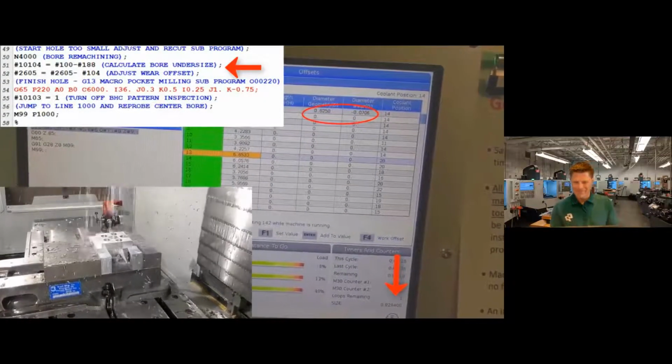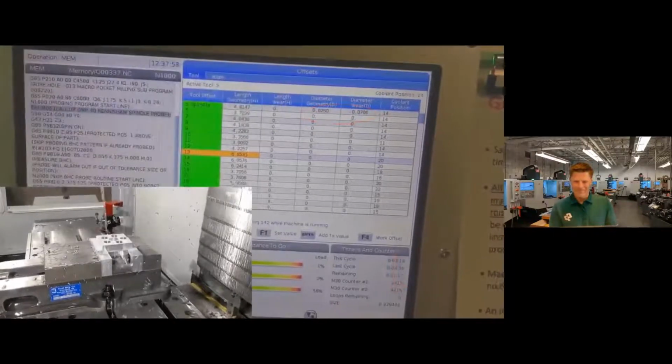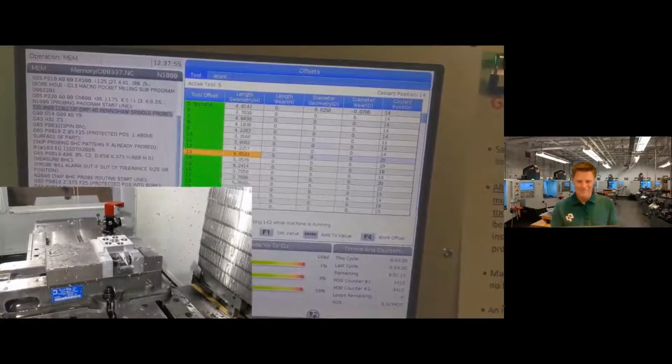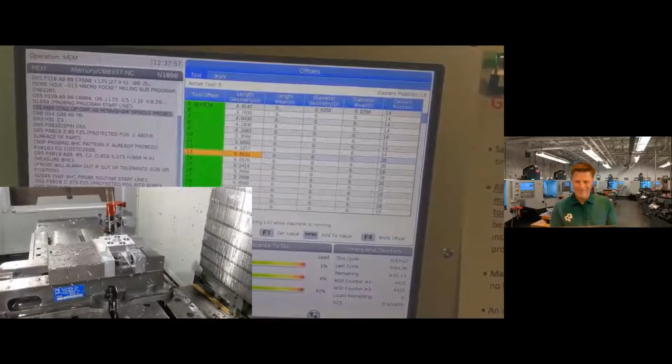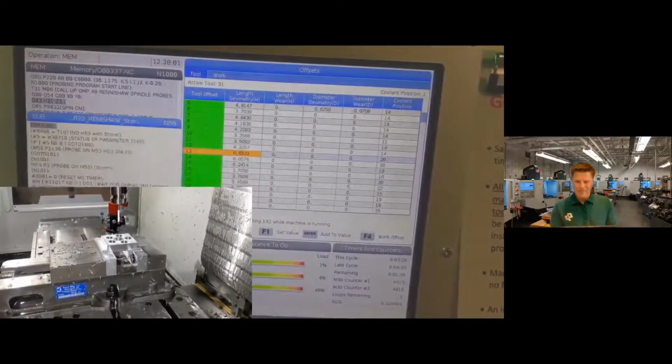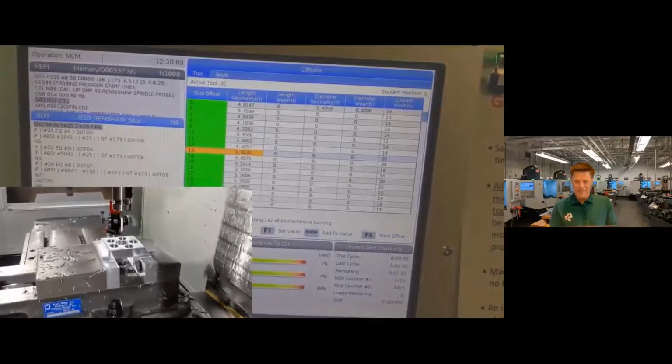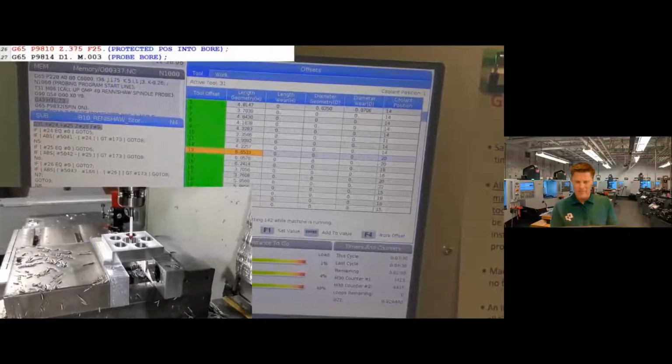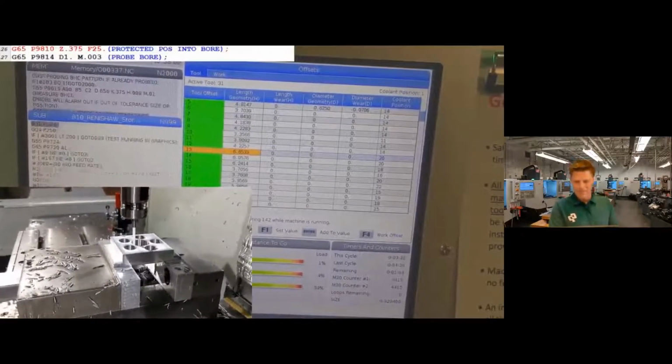It's at full depth because this was supposed to be a finished cleanup pass, by the way. So remember, it cycled different variables for the finish pass. So let's see what it comes out to now. I bet you it might have to cut it one more time. We'll see. That's just a high-speed steel dull end mill that we used for this project, for this demo.